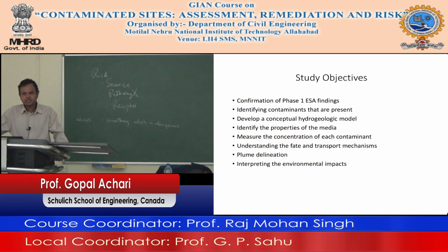So what are the study objectives of a Phase 2? Confirmation of a Phase 1 ESA. Identifying contaminants that are present. Remember, it can be anything, right? It can be diesel, it can be gasoline, who knows what is there, especially in areas used for disposal of waste product. You don't know what they disposed of, right? Metals.